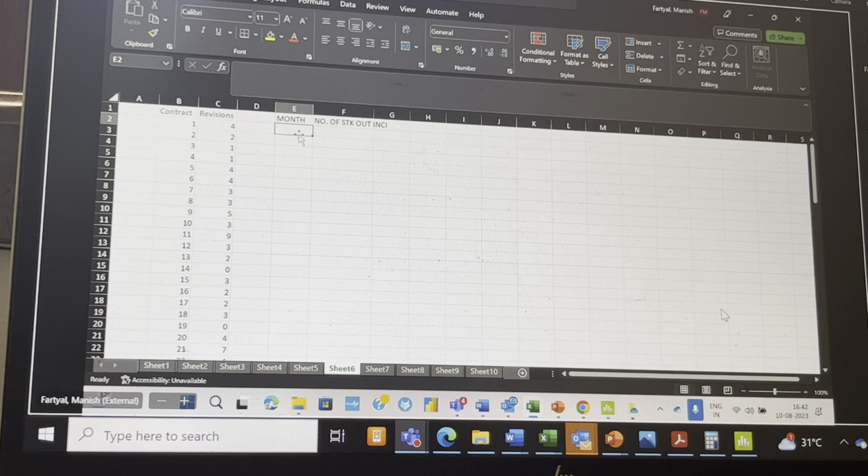The defectives is clear, sir. Only that subgroup, because for example, for SPC, suppose you are doing hourly inspection, so we take 5 samples. So every 1 hour there is a subgroup, a subgroup of size 5.